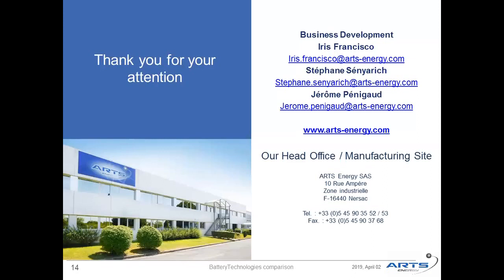The next question is about nickel metal hydride. The question is that the electrolyte is water, so how can you charge below 0? In fact, the electrolyte is not water, it is aqueous, but it is not pure water. It is a very concentrated alkaline solution. And so the freezing temperature is not 0, it is around minus 50 degrees C. And so you're right that the key point is the temperature where the electrolyte freezes. So I would say down to minus 45, down to minus 50, we can use the battery because the electrolyte is not frozen.